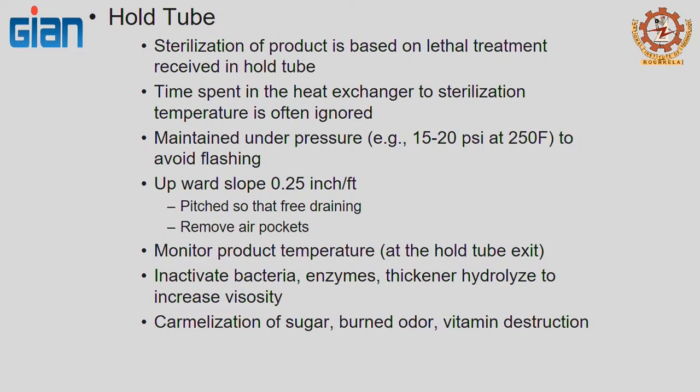Holding tube. So, at the heart of aseptic processing is the holding tube, because this is the place where you determine or demonstrate the lethality of your product. It does not matter how much time the product spent in the heat exchanger; you do not consider the lethal effect, only the time spent in the holding tube. So, 30 seconds, 50 seconds, whatever it is based on your design, that is what is going to be considered.